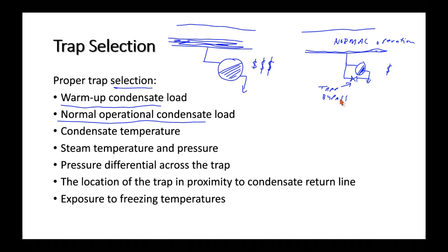And I know that you have all operated trap bypass valves in the Cenovus lab on the main floor. There's trap bypasses. You warm up a steam line, you open up the trap bypass. Now, there may be some plants where you've got a trap that's hard to get to. It's the end of a steam line or something like that. There may be places where they size a trap for automatic warm-up. But where there are operators present and the operators are on site during the warm-up, we'll have manual trap bypasses. So this would be for a manual warm-up.